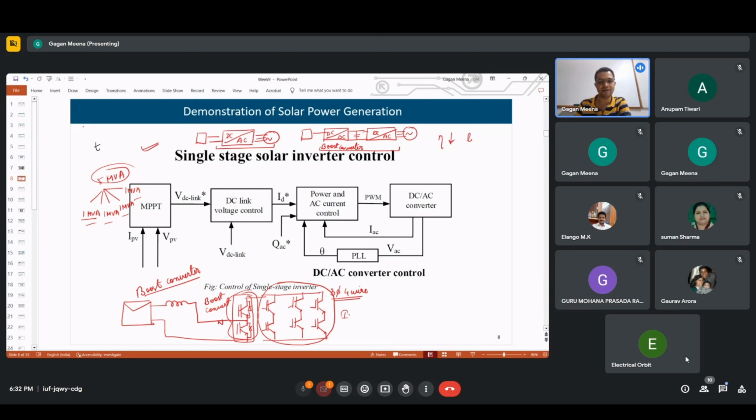this is one type, a dual stage converter with a three-phase inverter. Just as in HVDC we have back-to-back converters, right? In back-to-back HVDC, in one station we have two converters. That is why the rotor side converter and grid side converter in a DFIG are an example of a back-to-back converter.